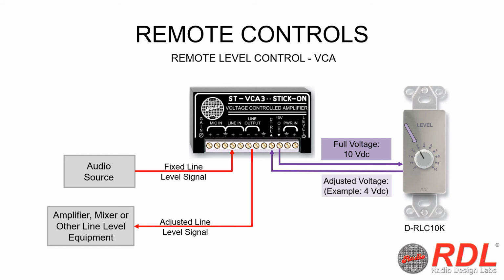Here's the advantage. Again, conventional audio pots or volume knobs are different in that the actual audio signals pass through them directly. They have 2 primary components, a fixed resistive element and a sliding contact wiper that contact each other. By turning the knob, the wiper slides along the resistive surface from one end to the other, which adjusts the audio signal level. However, these contacts are subject to wear and carbon buildup, which can greatly affect the audio signal quality during level adjustment, typically by producing audible pops and crackles or sudden jumps in signal levels. Since audio signals do not pass through VCA controls, the audio of the signal is never degraded and level adjustments will remain accurate and smooth for the life of the product.